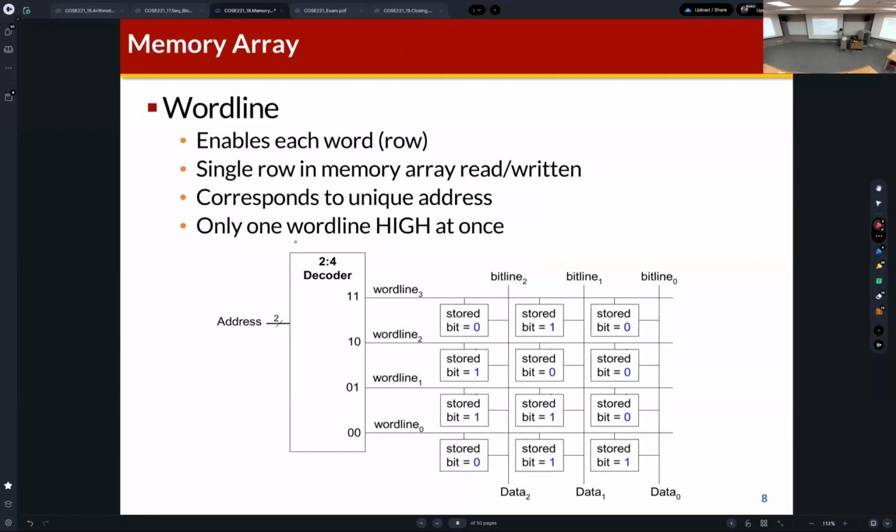If the memory includes many bit cells, then we can store a lot of data, right? So this is the detailed structure of a memory component. What can you see? You can find the data port here, and the width of the data port is 3 bits. Then what is the depth? You can also find the bit cells. Each bit cell is connected to the data port of this memory component, right?